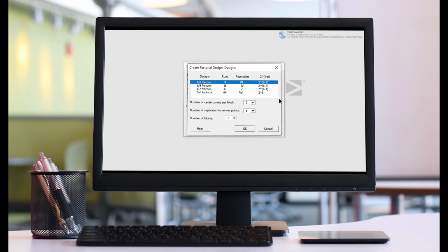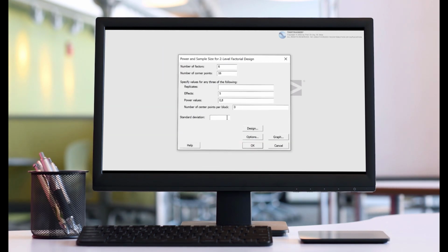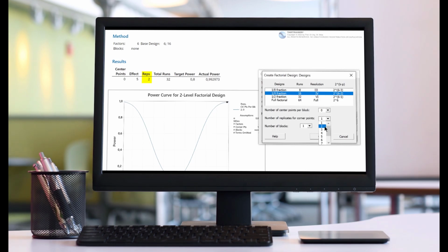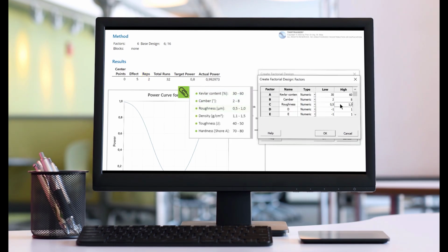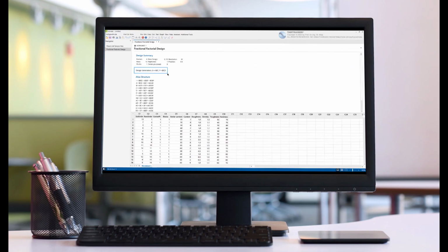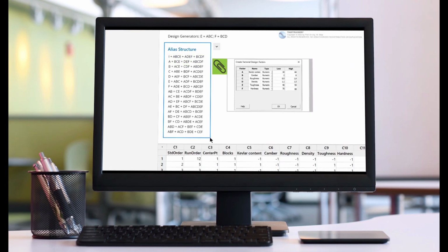Smartboard Company has a specially designed test station for this purpose, in which the skateboard wheel to be tested is fixed to an axle, driven by an electric motor. The skateboard wheel is then rolled on a counter body at a defined speed and a defined contact pressure. The surface properties of the counter body correspond to the properties of a typical road surface.